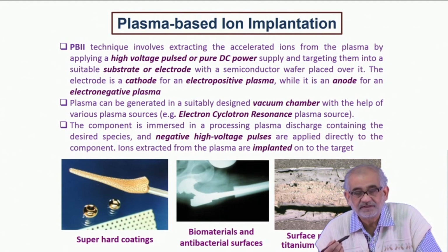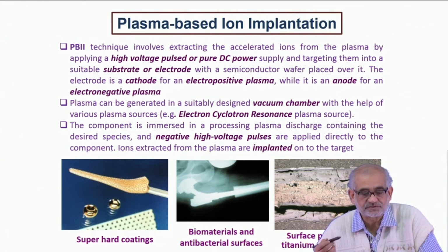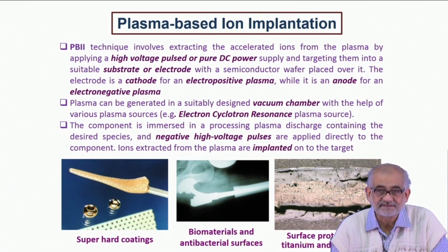So anything from Fe4N to Fe2N, a mixture of that graded from the surface to the core, and that's the reason why we get high hardness, high wear resistance, even fatigue resistance, corrosion resistance, and so on and so forth. So exactly the same.